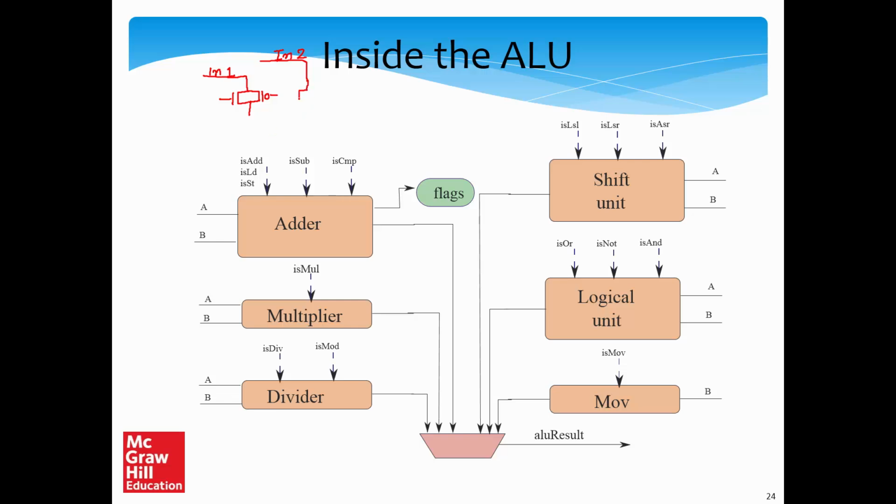So let's have two transistors back to back, and let this be the output line. Let the signal controlling this be A, and let this be the complement of A, which means both are enabled. Similarly, let this be B and the complement of B. This structure over here is called a transmission gate.